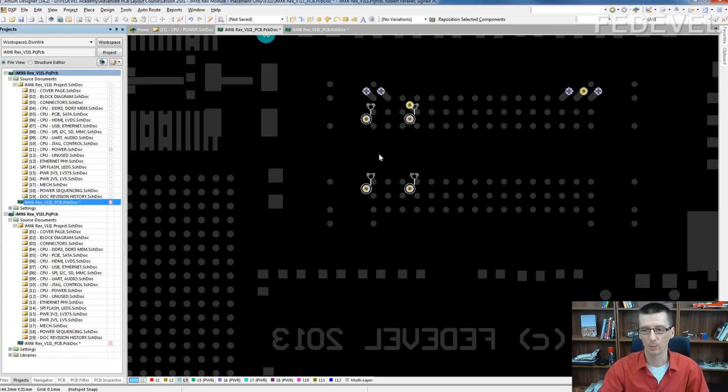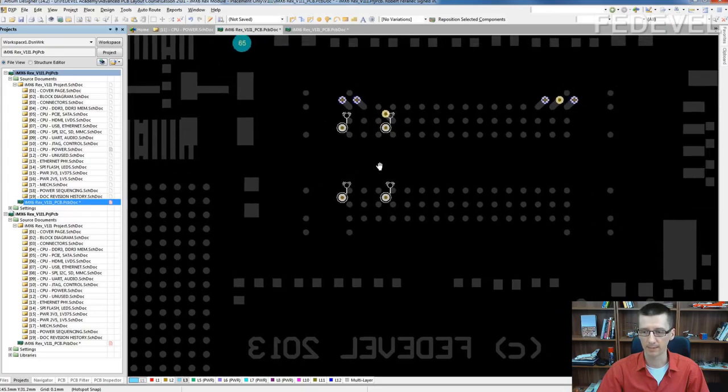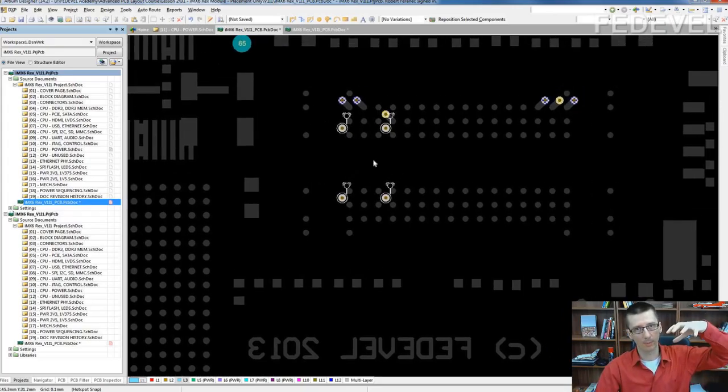You will see. We will speak about this special case next lesson, because this is the case when the top memory chip and the bottom memory chip are connected to the same data bus. They share the same data bus. On the module, we have the top memory chip connected to one data bus and the bottom memory chip connected to a different data bus. We need to use micro vias.